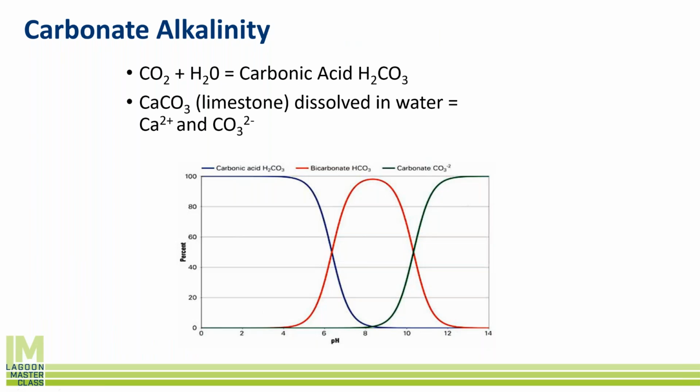Carbonate alkalinity, take you back to some high school chemistry classes maybe. So when your pH is under 6.2, most of the carbon that's in your water is carbonic acid. So obviously acid is not an environment that most living organisms like to live in. So we have carbonic acid in the water at that point, or carbon dioxide gas. It kind of goes back and forth between carbonic acid and carbon dioxide gas, finds another equilibrium. Between 6.2 and roughly 11, most of our carbon is in the form of bicarbonate. That's just baking soda, guys. That's just nothing but baking soda.